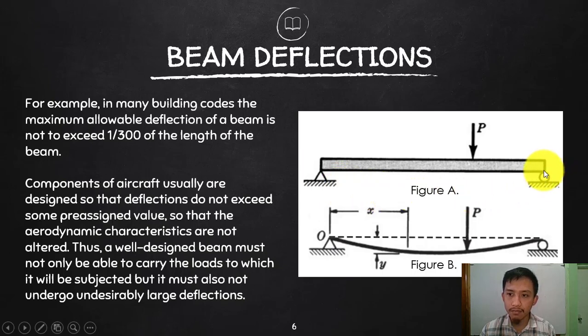At the same time, it should maintain a good posture and be comfortable. If this beam is, let's say, carrying a slab, and the slab is for a crowd, then the crowd on top of the beam will be comfortable because of the limited deflection of the beam.